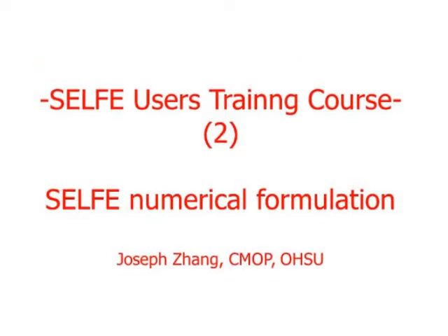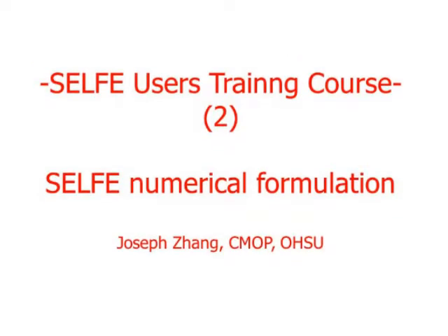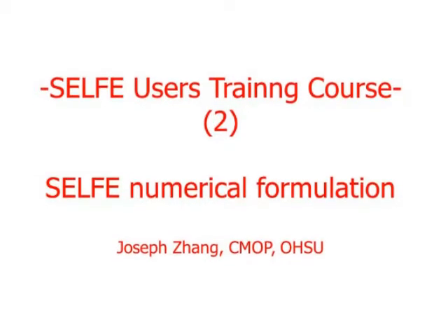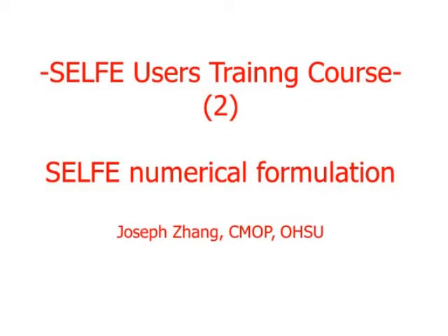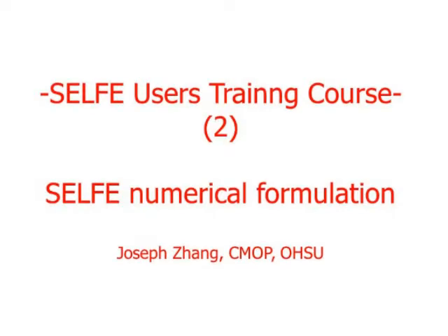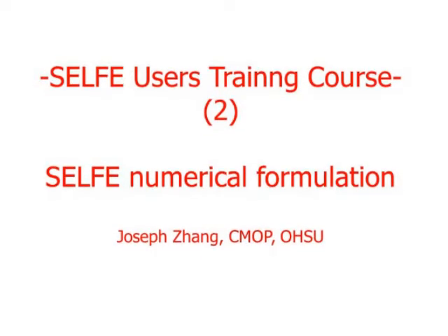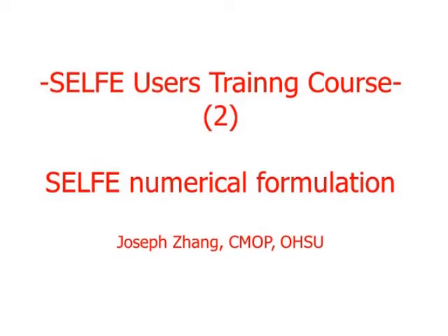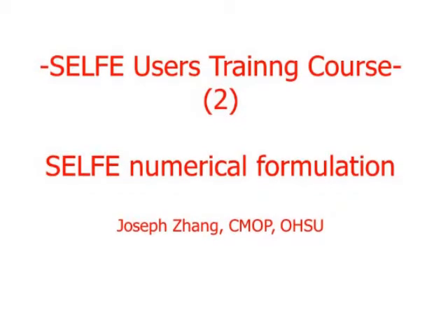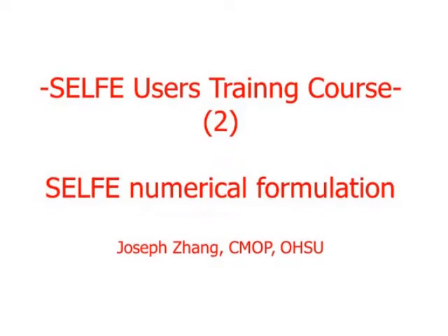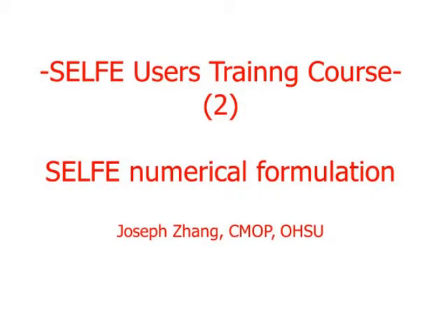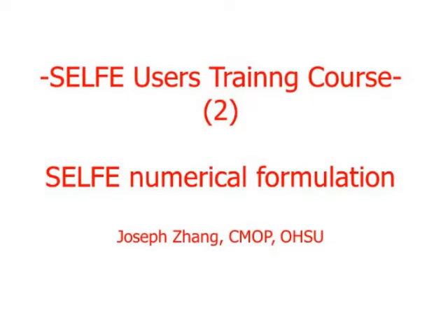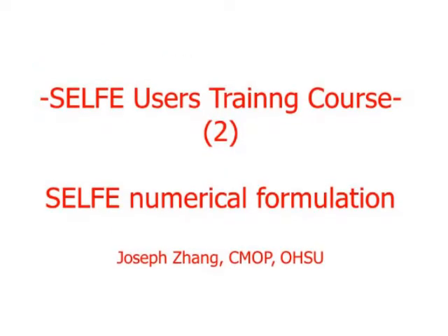Okay, slide number 19. This is another explicit term included in I4. It's the horizontal viscosity term. I'm not going to spend too much time on it because most of the time we don't even use it. The way we interpret this involves second order derivatives. We use linear shape function, so we cannot evaluate it directly. So we use Gauss theorem and cast it into this boundary integral.